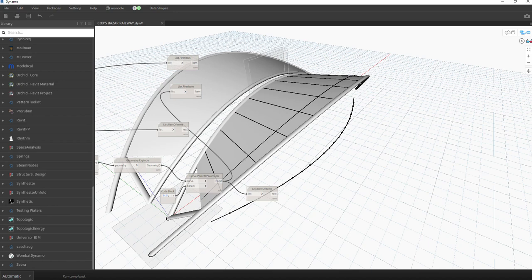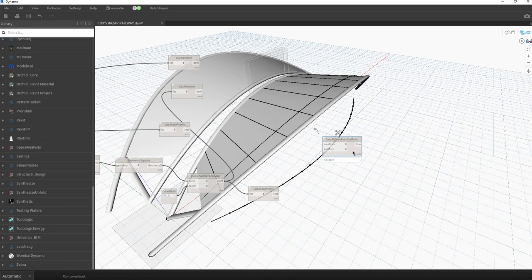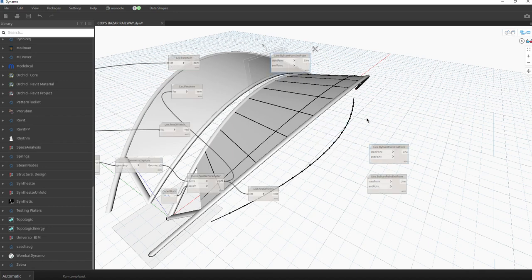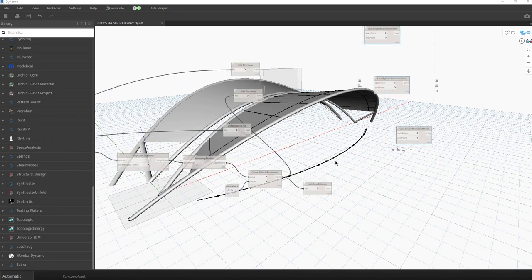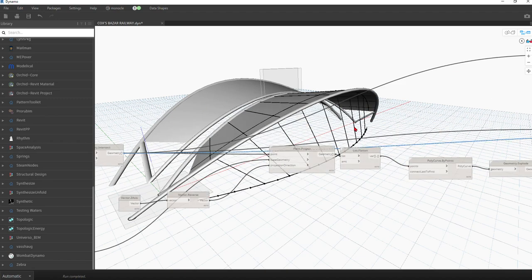Now if we create the line start by point, create a line start end point and start point. We need to create 2 times, Ctrl C, Ctrl V, Ctrl C and Ctrl V. Now this is the fun part, to create this bracing truss. Just connect this point to the end and connect to this intersection point.